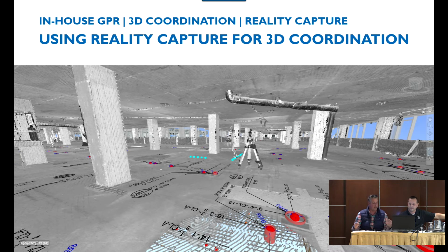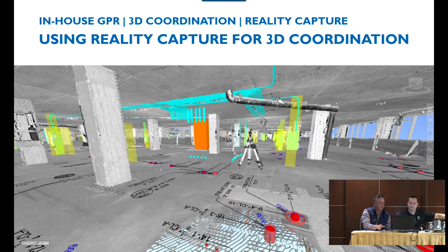His spheres come in, right? So we're able to go and show, hey, there's that point with the sphere. There's the core that needs to be relocated. So everything starts coming into play. On here, I don't have the colorization for deviation, but we're really worried about that plenum space. There's a very limited amount of space up there for all the mechanical equipment to go in. So we're able to start seeing where there's some deviation in the floors and in the ceilings that is going to interrupt our trade.